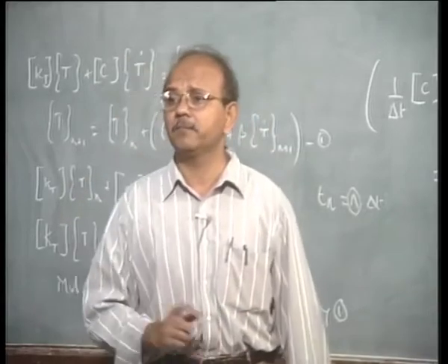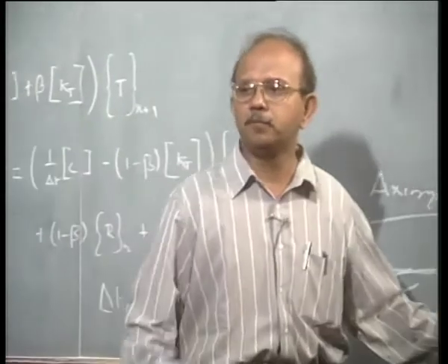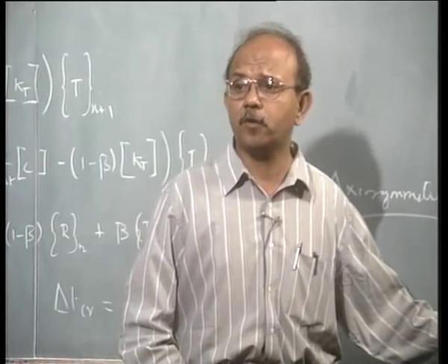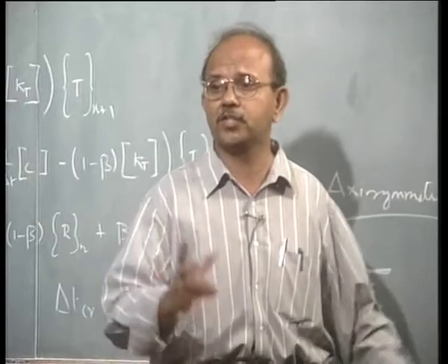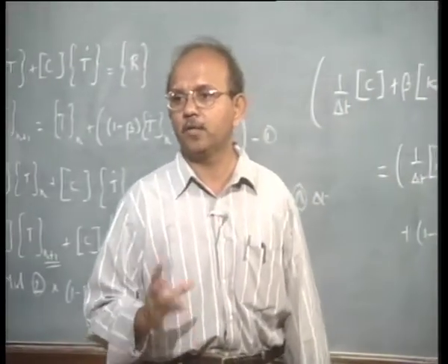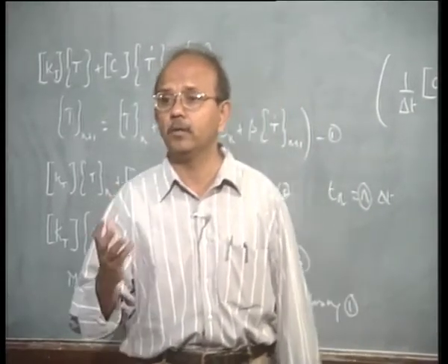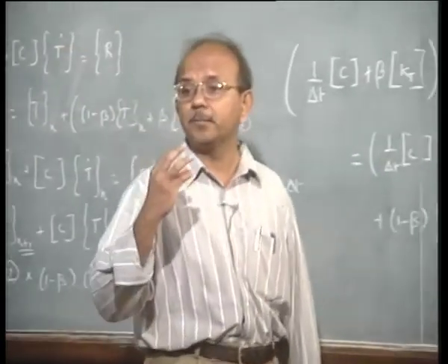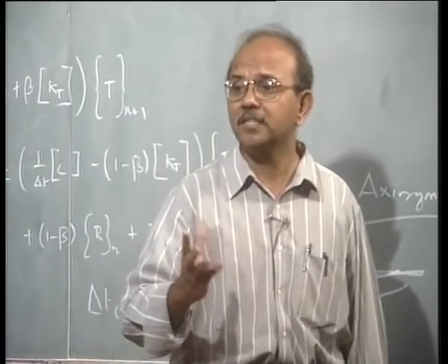So what does it tell us? It tells us a very important story: on one aspect there is mathematics, there is finite element. On the other aspect, there are other aspects to this process simulation which depend upon the process. So you need to have process knowledge. For example, you should know what is the power, what is the efficiency of the arc, what is the velocity with which this arc can move, as well as the material properties. All these things become important.